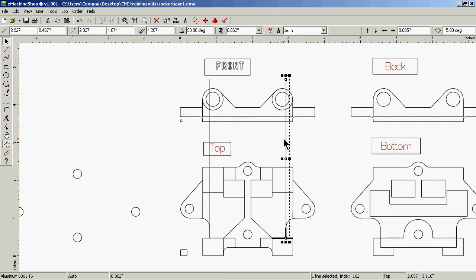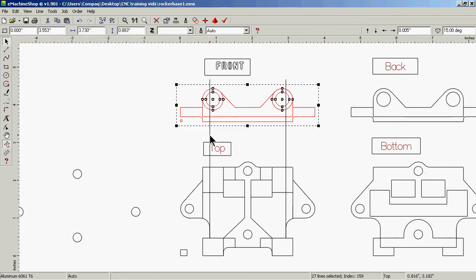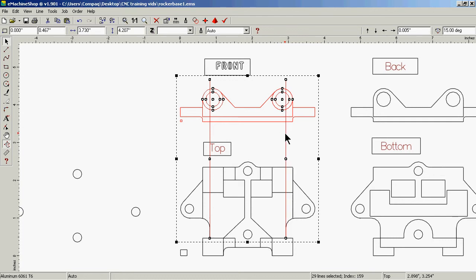All right. Now, in this drawing, I need to intersect these and take this corner out and then continue this line through. It doesn't actually do anything. I'll delete it out when I take this to the next print, but there's the difference in the drawing right there. This is not supposed to be here on the front end. So in order to do this, I'm going to have to select this area, hold down the control key, pick up these two lines, click intersect.